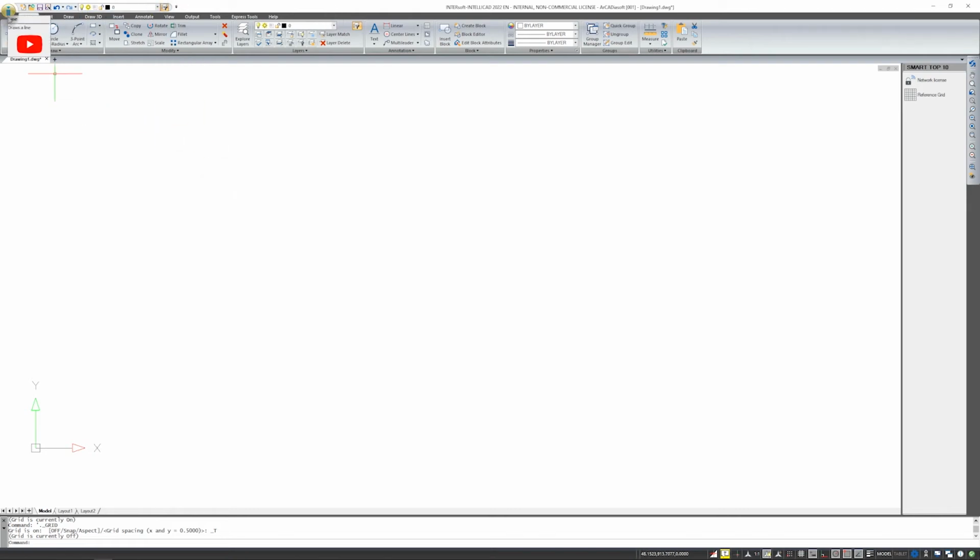I choose the line drawing option. In the previous video, I showed the basic options of data entry by using the input window next to the cursor. This window was turned on automatically when the drawing option was activated. You can draw in several ways. You can enter absolute coordinates in the Cartesian coordinate system, that is x and y. You can enter relative coordinates, that is from the point where you last drew. And you can enter relatively but polarly, that is adding, for example, lengths and angles, not just x and y.